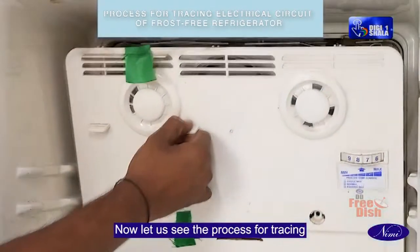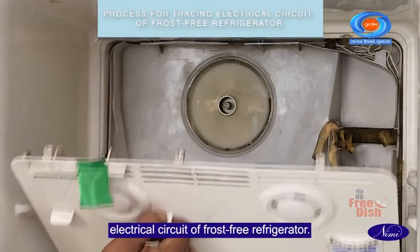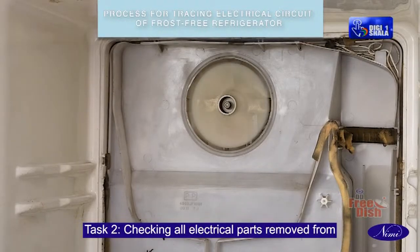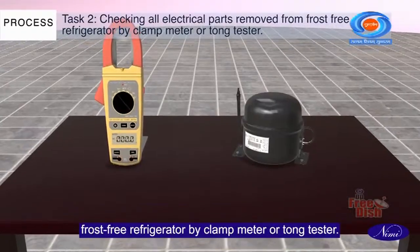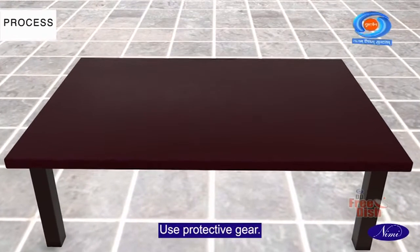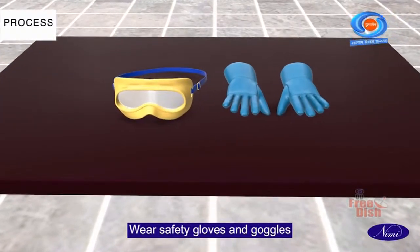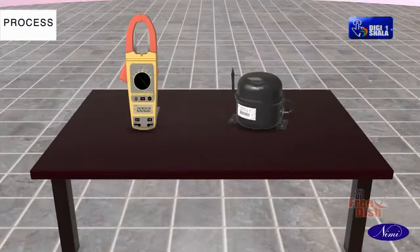Now, let us see the process for tracing the electrical circuit of a frost-free refrigerator. Task 2. Checking all electrical parts removed from the frost-free refrigerator by clamp meter or tong tester. Use protective gear. Wear safety gloves and goggles to protect against potential hazards.